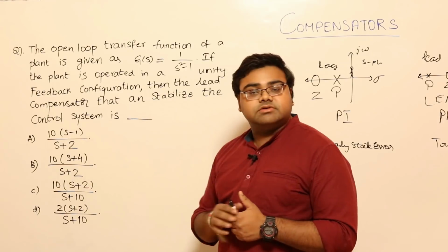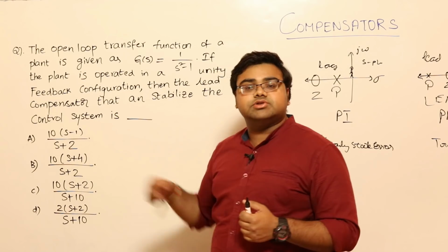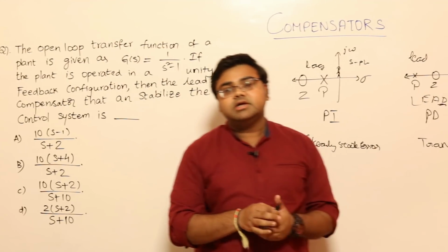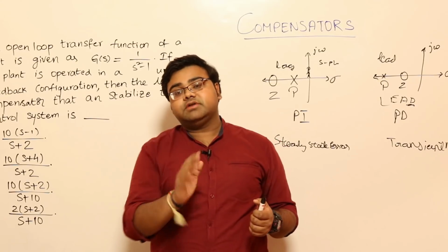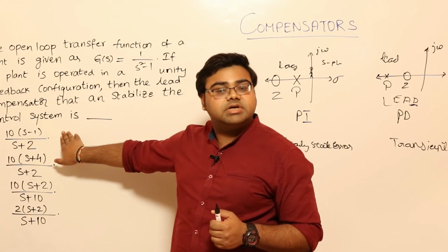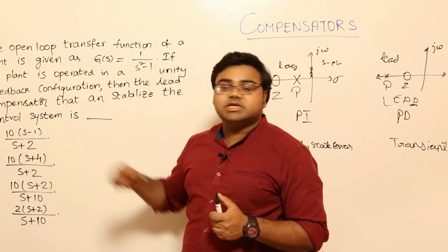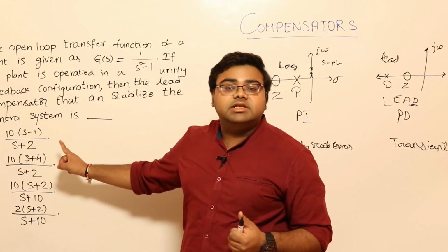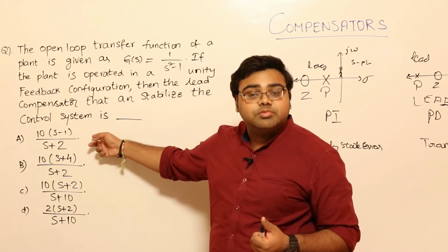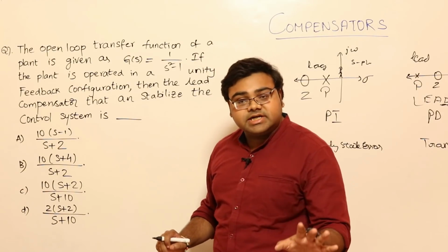1 is there, that is nothing but the 0 at minus 2. If you were to stand here or anywhere, the 0 is either behind you or in front of you, that is lead. The pole is lagging, so this is a lead compensator. But is this a lead compensator or not? I will tell you. The problem is this is unstable. You cannot design this. This is not a design, this is improper. So this is not a correct answer at all, rejected.